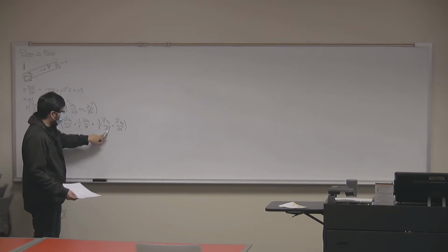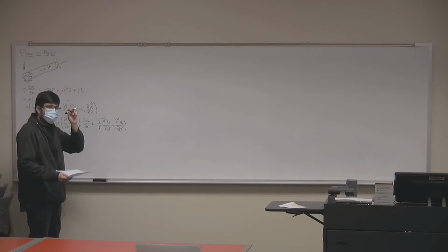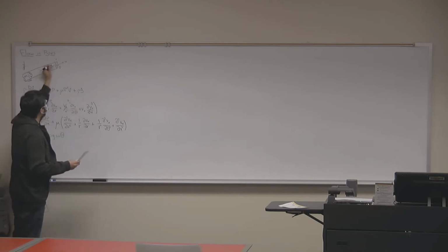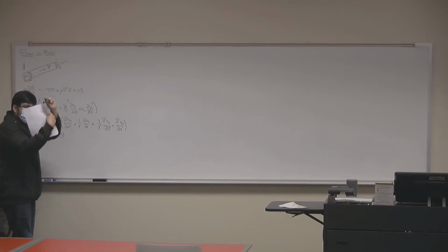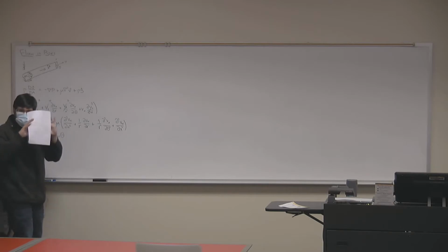We don't have any change in velocity in the angular direction because this is a symmetrical system, right? So the velocity, if you're at some distance from the center, it doesn't matter where in the pipe you are. If you are at the same distance from the center, your velocity won't change. Does that make sense? Notice that the velocity at the walls is 0, and then it starts to increase parabolically until it reaches the velocity at the center.